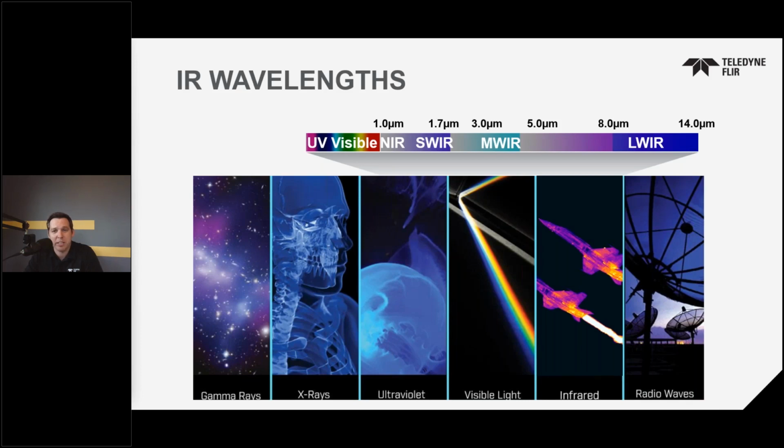Due to its proximity to the visible spectrum, SWIR is great for exploiting characteristics of material that we're used to in the visible spectrum, such as imaging through glass. Alternatively, SWIR detectors can also see through surface coatings like paint to inspect the materials below and see through atmospheric constraints like haze. Another aspect of being close to the visible spectrum is a really high noise floor for thermography applications. So factory calibrations, if you can even get them, typically have a starting point of 400C, maybe even higher. At FLIR, it's 400C.